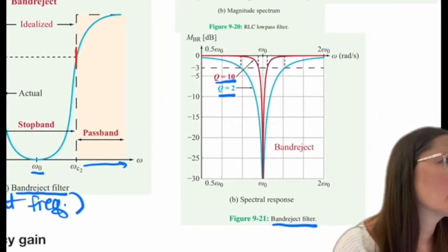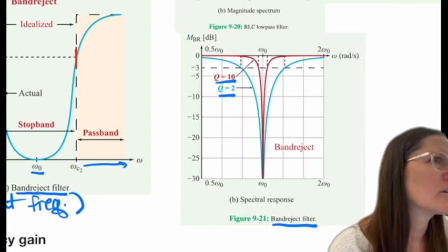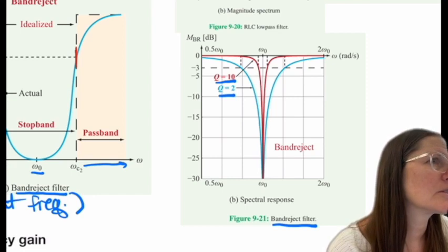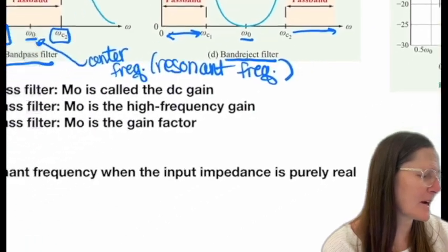Yes. So in general, a high Q factor would be ideal for a very specific band pass or band reject. But you sort of want more of a low Q on a high pass or low pass. We didn't want that sharp spike in sensitivity right before the corner. Correct. Yes, you are right.